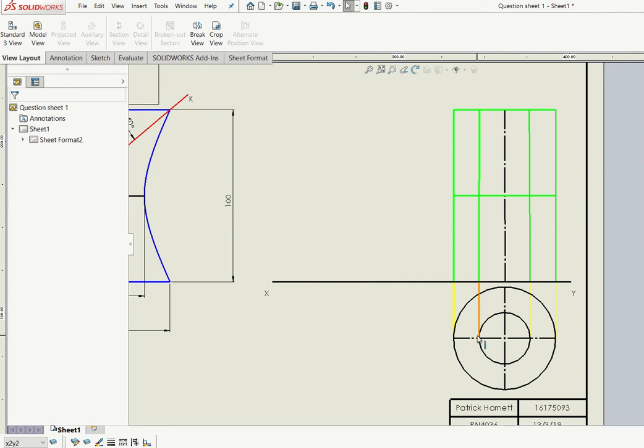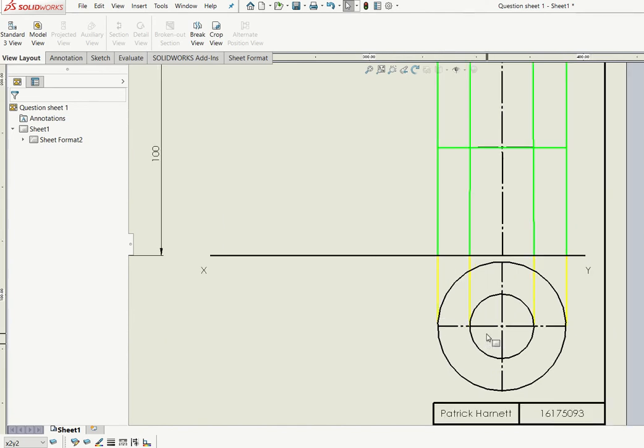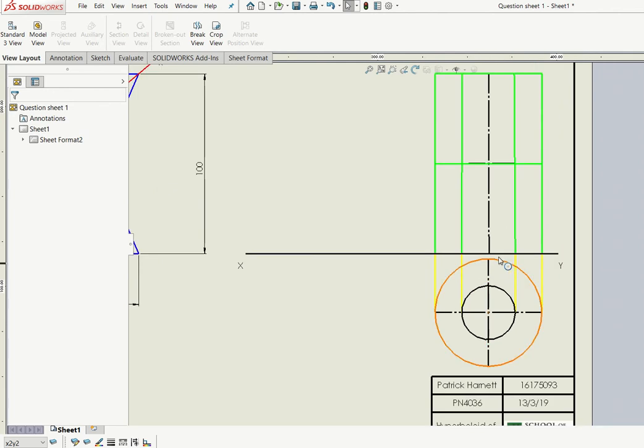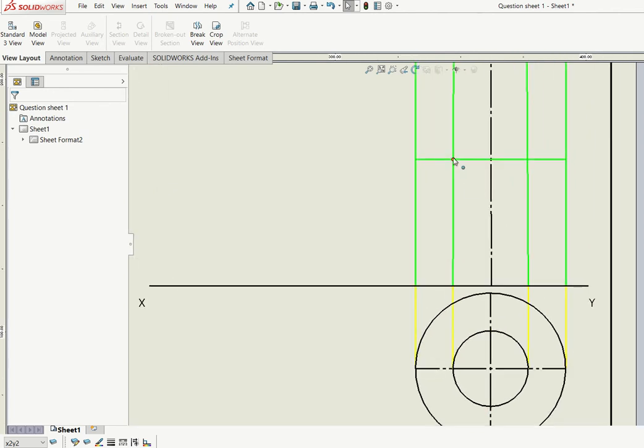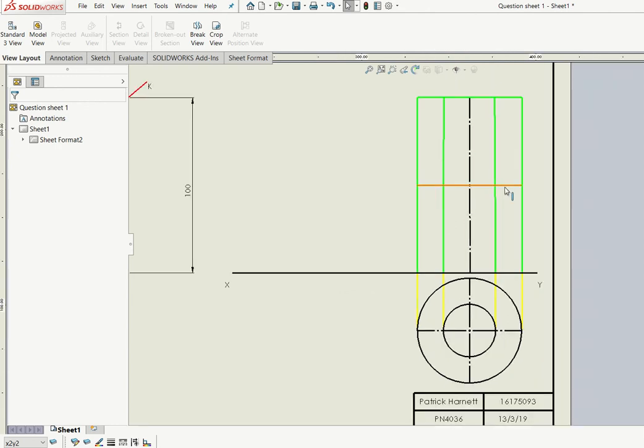So these rectangles are going to be made so we can create a double hyperbola on either side of our center line. So firstly, we're going to bring up our yellow lines here, which will give us our widths. So we know that the points on each side of our throat circle will give us two vertices. So we'll have vertex 1 here and vertex 2. So if we project up these widths, then on our center line here, we're going to get vertex 1 on the left and vertex 2 on the right. By drawing across our center line to the outside of our rectangles, then it'll allow us to get a rectangle here on the top left, top right, and bottom right.